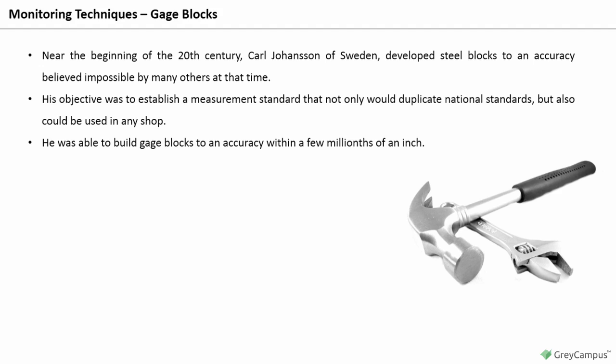Gauge blocks should always be handled on the non-polished sides. Blocks should be cleaned prior to stacking with filtered kerosene, benzene, or carbon tetrachloride. A soft, clean cloth or chamois should be used. A light residual oil film must remain on blocks for ringing purposes.